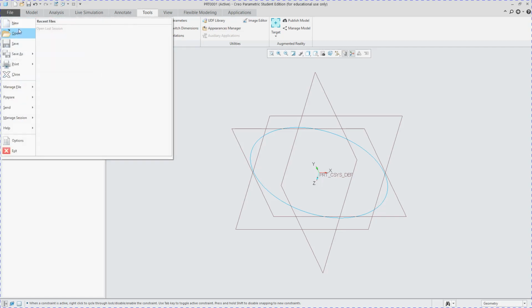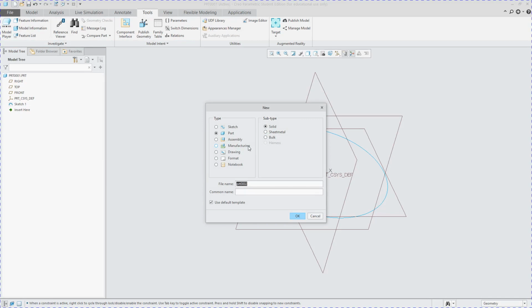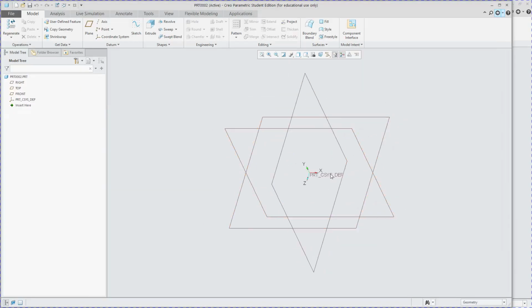So first thing I want you to do is open a new part. Now it's very important that you work in the XY plane because the basic gear equation that I'm going to give you, that I'll post up in the week's notes, is based around involute curves in the XY plane. You can do it in the XZ or the YZ planes, but that just requires changing things, and it's frankly unnecessary.